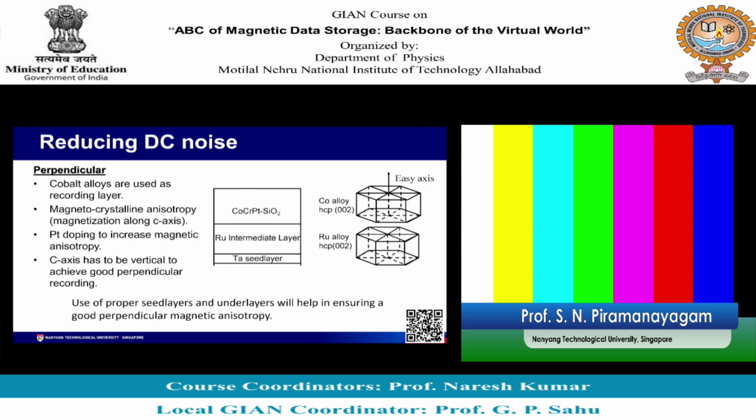Okay, so that is the reason why we have ruthenium layers. Basically, this seed layer here I showed tantalum, in the other slide I showed you nickel tungsten. Tantalum was very old technology, like 20 years ago, nickel tungsten is a later technology. So, by having this seed layer, you can maximize the ruthenium grains which have C axis orientation perpendicular.